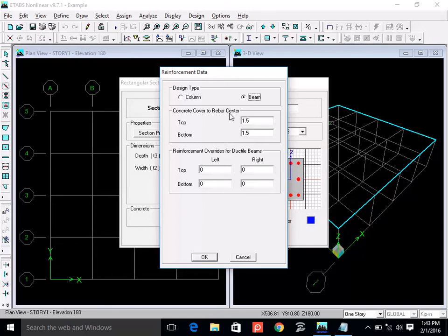Okay. And the longitudinal bar has variation. The longitudinal bar in beams is generally either number 13 or the next one, number 16, up to number 20.